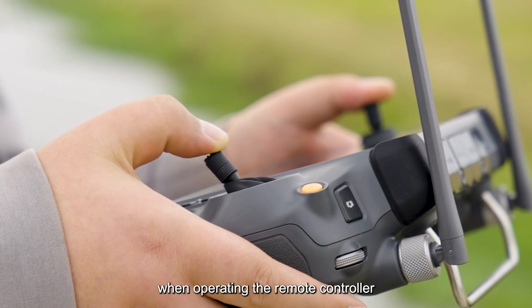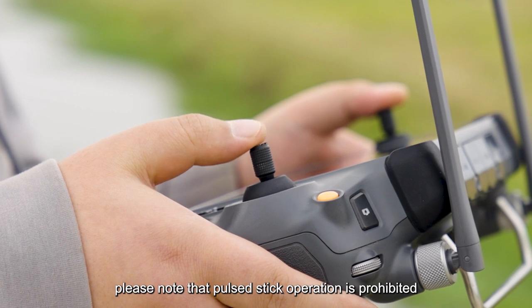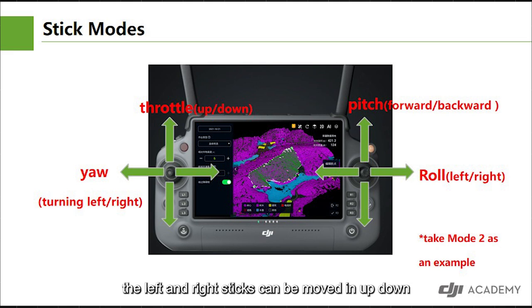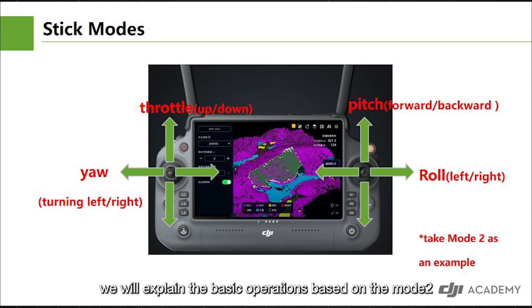When operating the remote controller, please note that pulsed stick operation is prohibited, and fingers are not allowed to leave the sticks during manual flight. The left and right sticks can be moved in up, down, left, and right directions respectively, with the corresponding 4 actions of the aircraft: flying up, down, turning left, right, flying forward, backward, and left-right lateral movement. We will explain the basic operations based on the mode too.